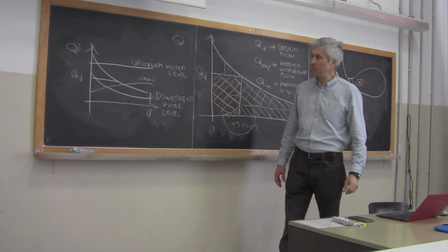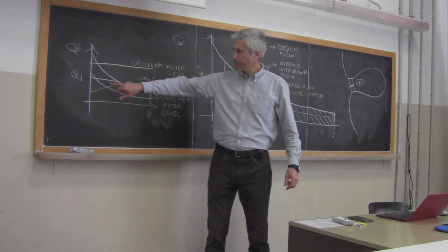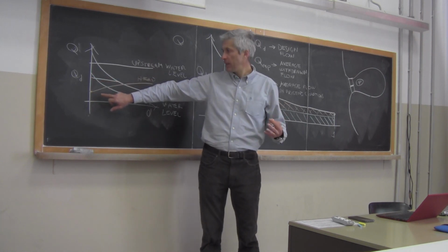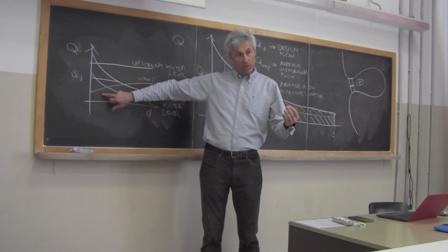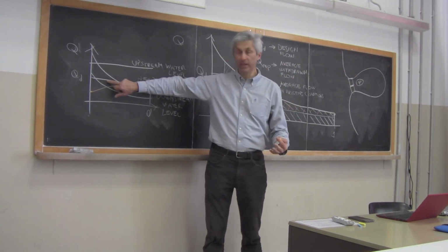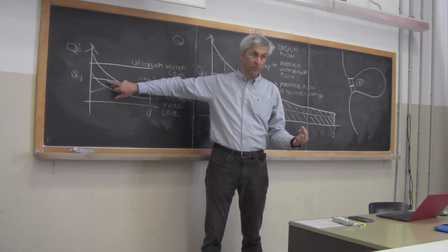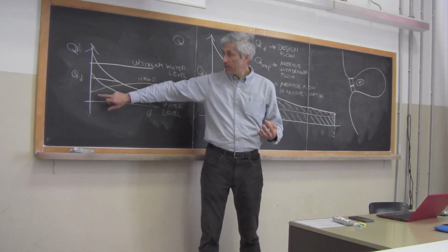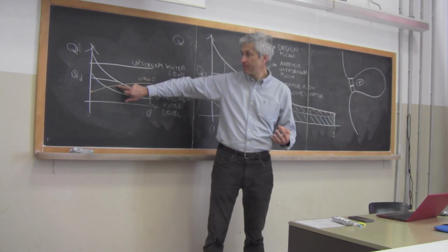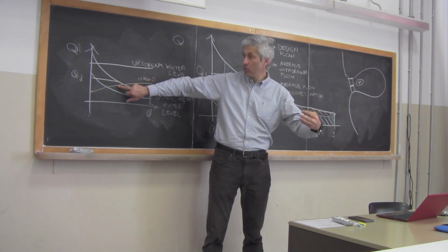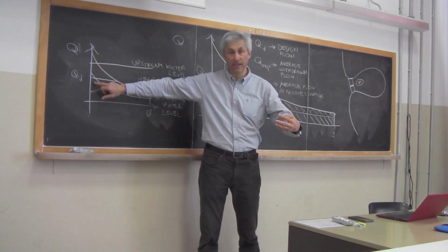So what does this mean? It means that for the highest flow, you have a reduced head. So when the Po River is in high flow, you cannot increase the design flow of the turbine, and therefore energy production is lower. The head increases, and therefore the energy production increases, when the natural flow lowers down.